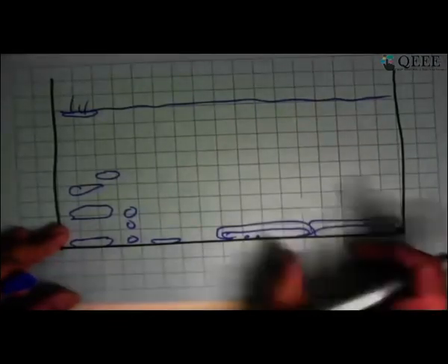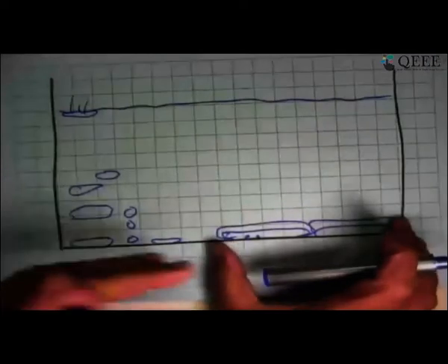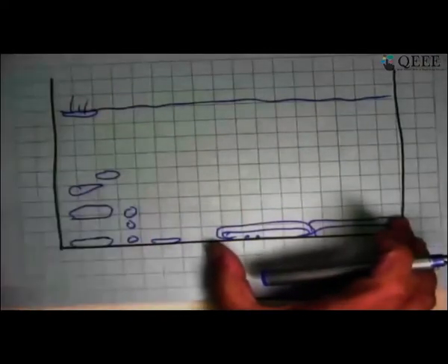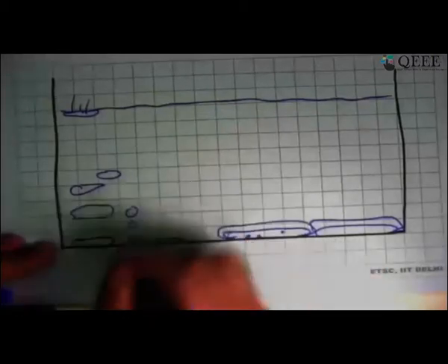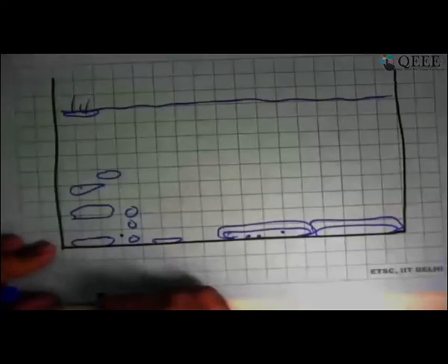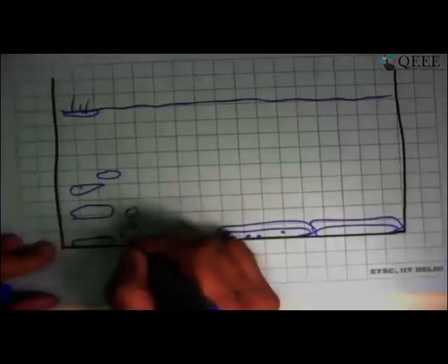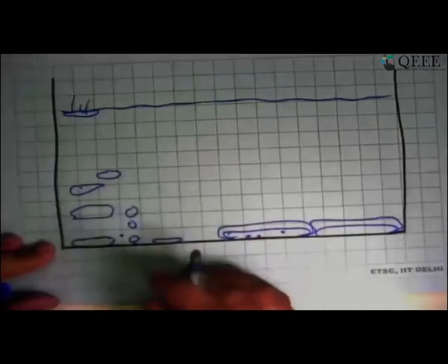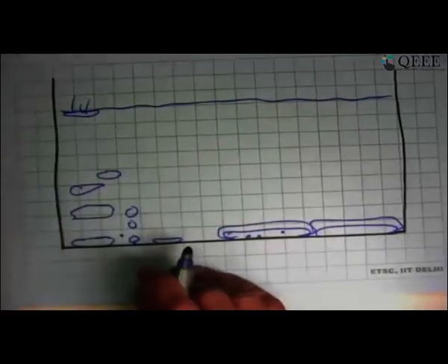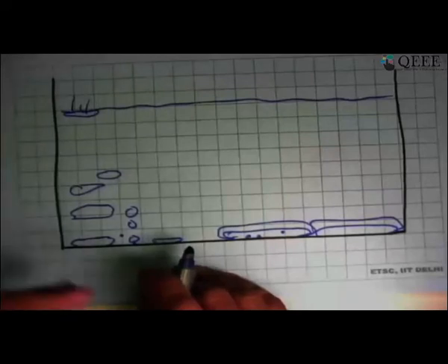So the fluid, the surface now is increasingly seeing itself in contact with vapor, whereas when it was nucleate boiling, it was largely in contact with liquid, and occasionally when the vapor formed, it would break off and go away, bringing in more liquid in contact with the surface. So more and more of liquid was coming in contact with the surface.